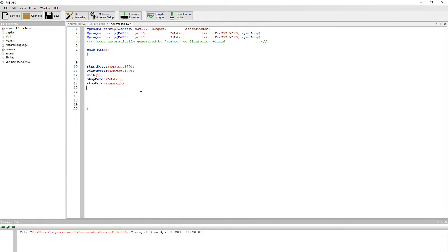The great thing about motors is you can control them a little bit differently. So like, let's say I wanted to turn to the right. And when you think about a robot, the robot has 2 sets of motors connected to each wheel. So to turn right, what I can do is I could either just turn on the left motor. So I could just turn that on, and it's going to just run the left side, which will make the whole robot turn right, which is one way.